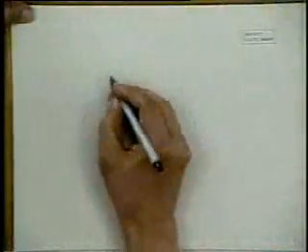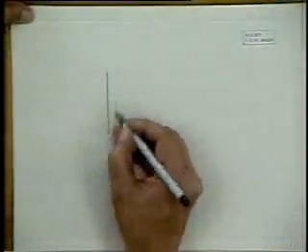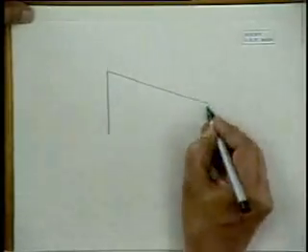Today I'll continue with the waveguiding aspects. In the last talk, we discussed what the confinement factor, gamma, was, and we showed that only a part of the light that is emitted in a slab waveguide is contained in the active region. Now let's look at the perpendicular geometry. Let's look at a three-dimensional view of a laser.